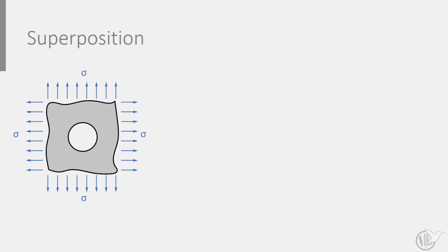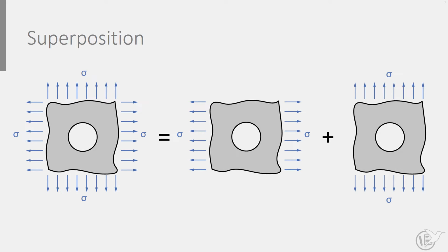The definition of the stress concentration factor relates to uniaxial loading. In case multiple directions of loading are present, a superposition principle can be adopted. Stresses can be superimposed, which means that effectively the illustrated biaxial load case should be considered as two uniaxial load cases that are superimposed. For the case of biaxial tensile loading with both loads equal in magnitude, the effective peak stress imposed by loading in one direction is reduced by the load component in the other direction. Hence, the stress concentration reduces to 2.